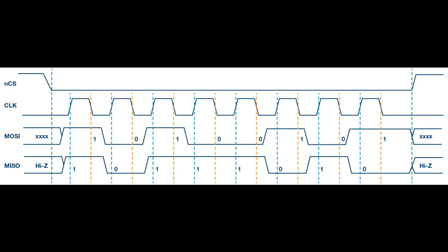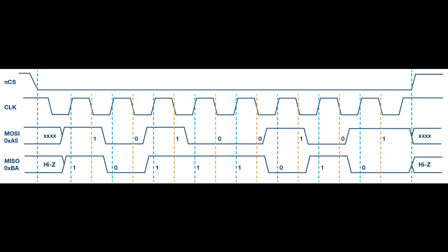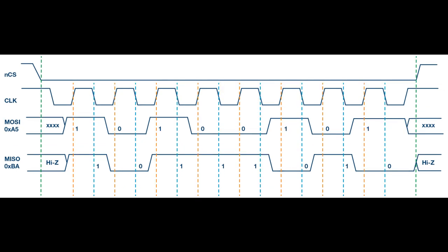For example, in UART communication, both sides are set to a pre-configured baud rate that dictates the speed and timing of data transmission. The clock signal in SPI can be modified using the properties of clock polarity and clock phase. These two properties work together to define when the bits are output and when they are sampled.